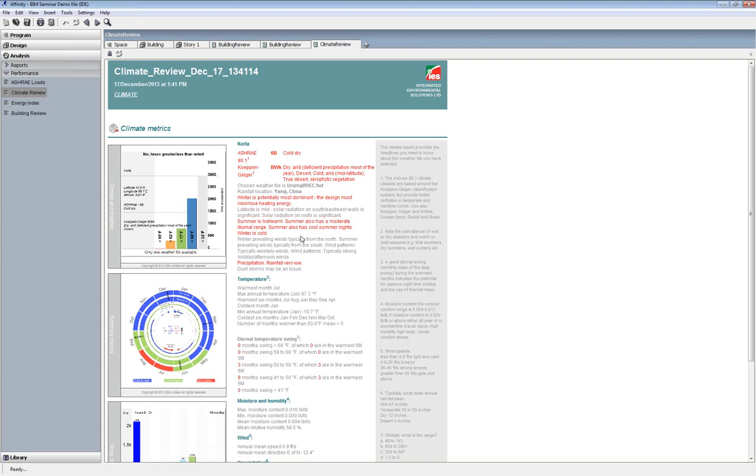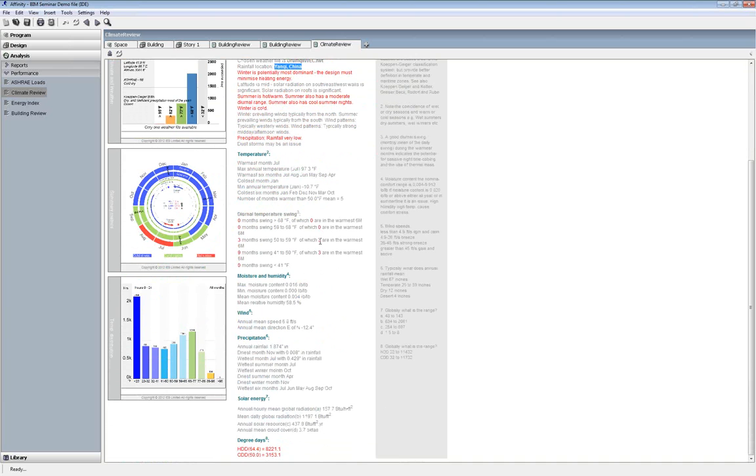All right, so here's an example of a report. It gives you the information based on the location. The latitude and longitude that I put in is in China. But it starts to tell you the heat days versus the cold days, the degree days, and that information so that you could do an early energy analysis based on your building and determine how you want to actually design your building.